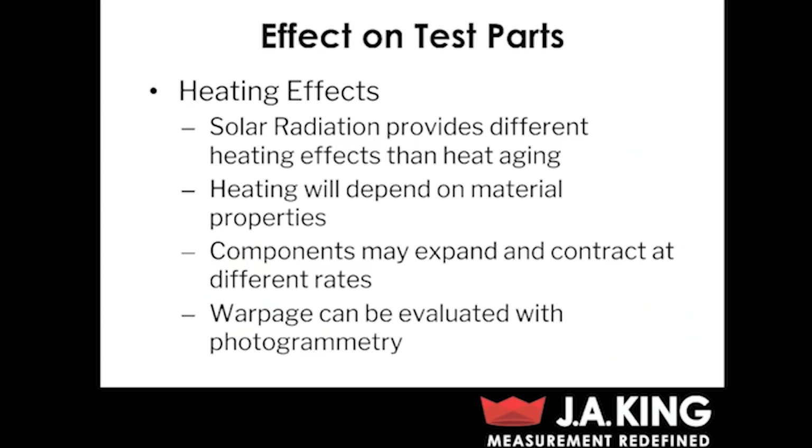And this is going to depend somewhat on the actual material properties. The different materials are going to have different absorbance and reflectance properties. So that's going to affect their heating during testing. And because of this, you're going to have components that might expand and contract at different rates. So this is going to potentially cause a lot of stresses at component interfaces. And ultimately, all of this can lead to warpage.